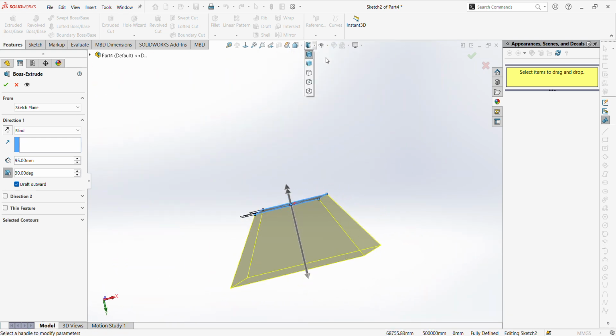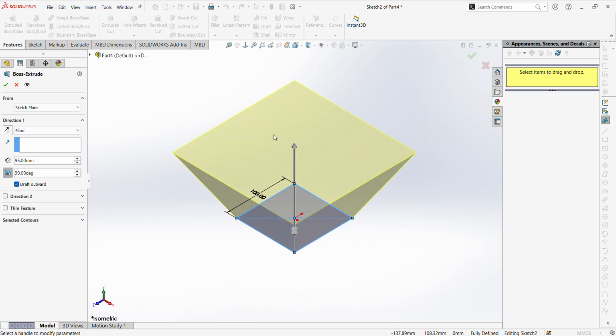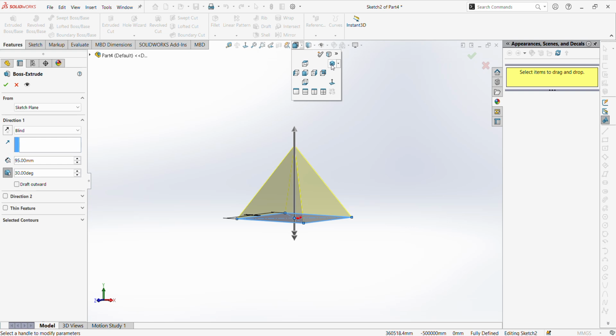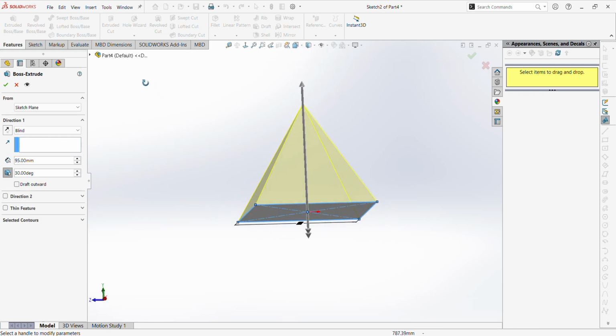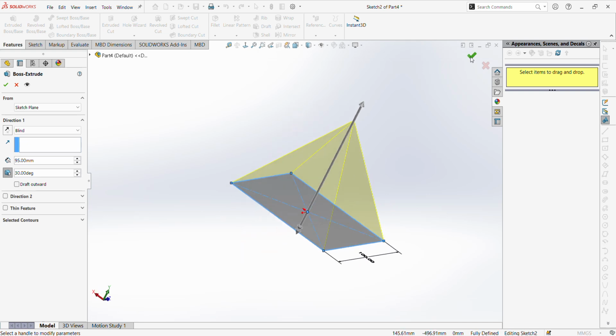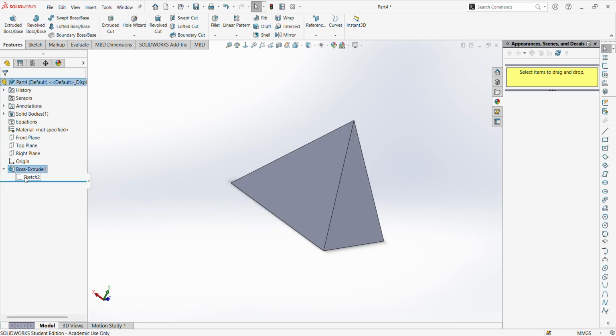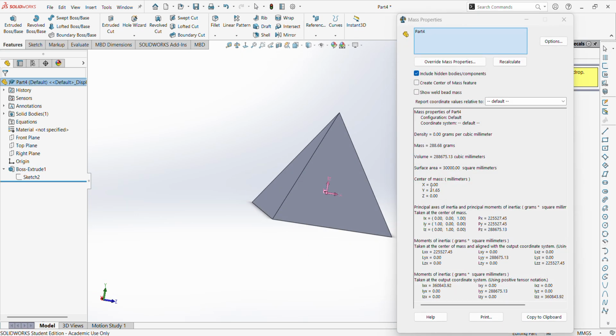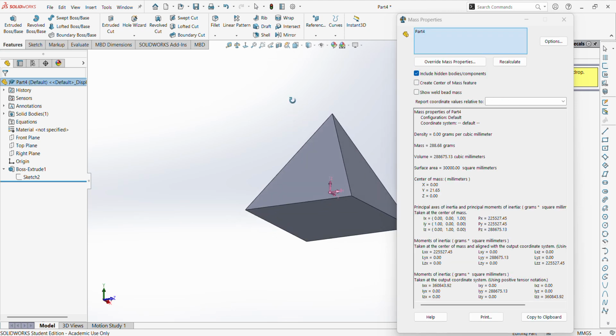But the difference being, when we look at it in ISO, how it would sit on the table, correct? So if we flipped it the right way, now it's sitting on its table and the pyramid is going upwards, because that makes sense. So cool, that is a simple pyramid. We can end that, and because we used that center point rectangle and extruded off of the center, our center of mass is going to be a little weird. It's only going to be in the y direction because we're flat on the plane and it's center, and everything should be from that bottom.